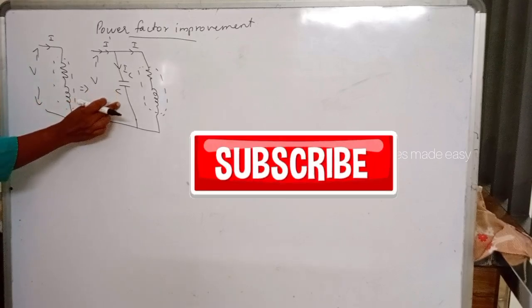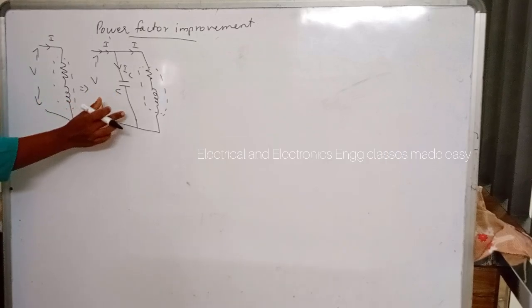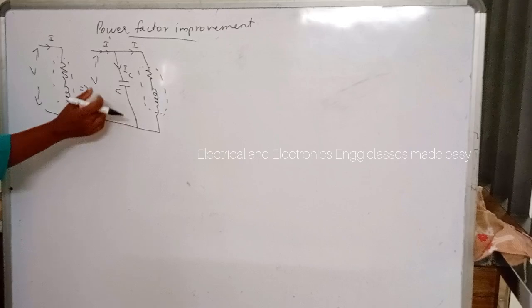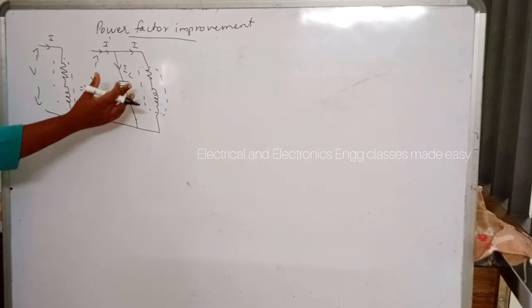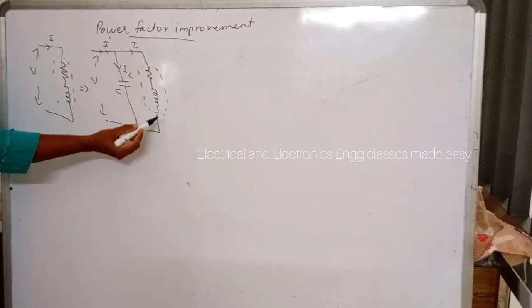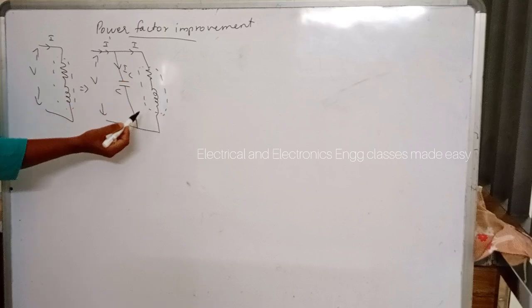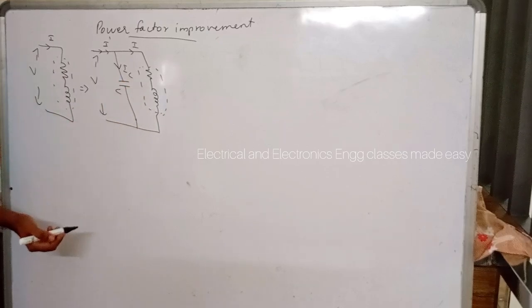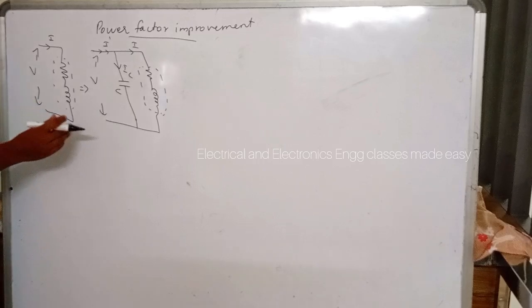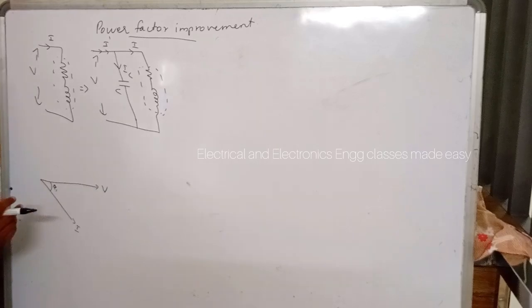The capacitor draws a leading current and partly or completely neutralizes the lagging reactive component of the load current, and this raises the power factor of the load. So, let us illustrate the power factor improvement by a capacitor.